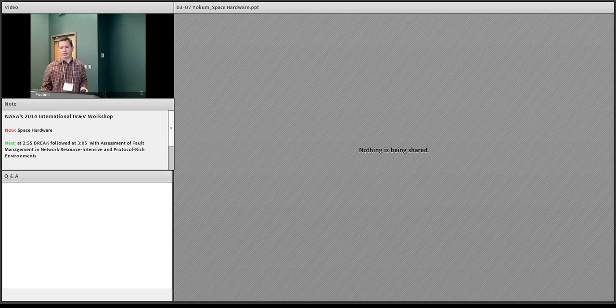JPL asked that IV&V look into this and see what we could figure out. So we took this to the software model and immediately found out that we couldn't get anywhere with that. The ISR just wouldn't show up the same. This wasn't working out. So we moved a VxWorks 6.4 image, which is what they run on Juno, and took it to the RAD 750 with a little test driver to see if we could get some of this same behavior to occur.